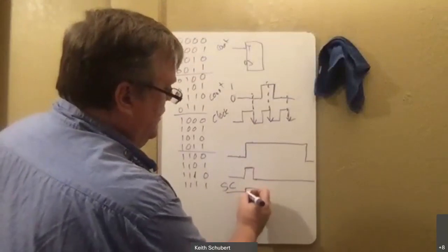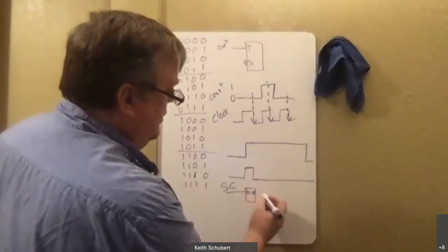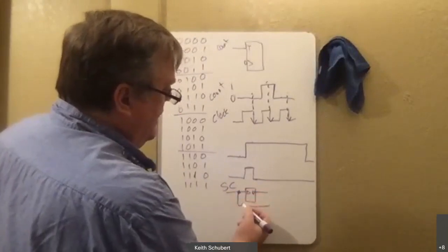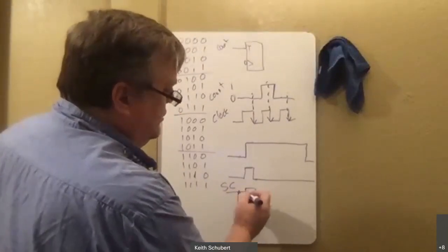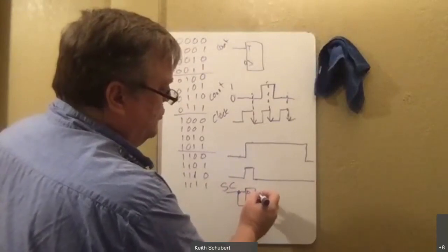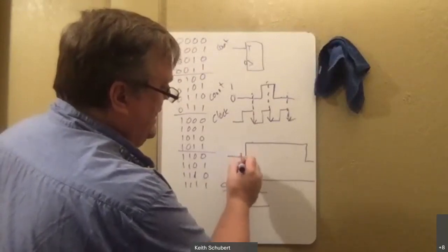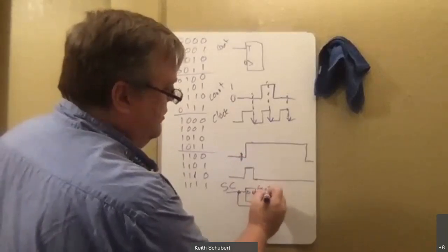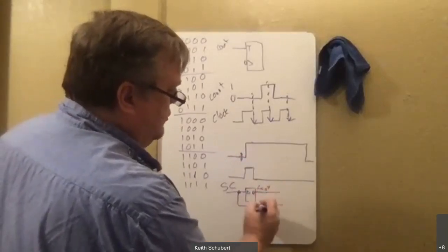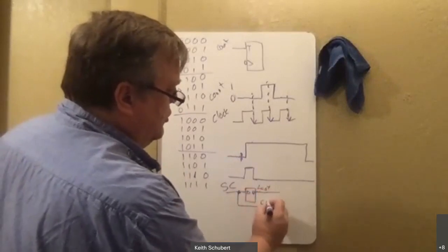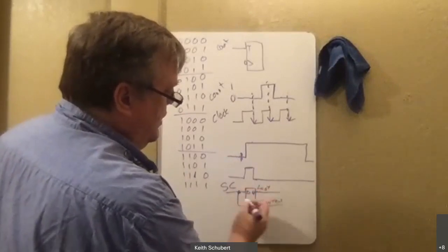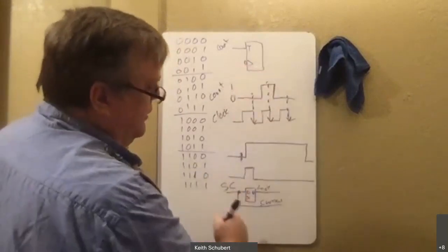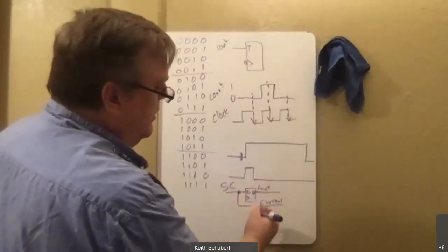I run it into a D flip-flop. And I compare, right? So this has some latency. So in here is whatever it was last time period. And this one, so this is last. And this one, there's no delay, so it's the current. The clock on this is whatever clock you want to go to. So this will end up being a single pulse.